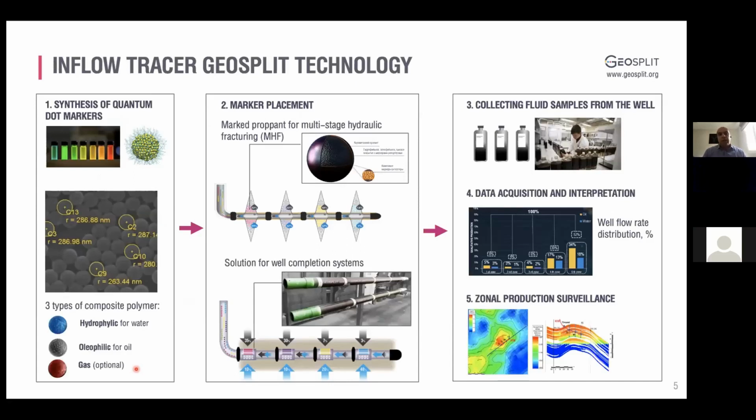I'll start by explaining the inflow tracer technology workflow. As I mentioned, what we use as a basis is quantum dots, which are nano-sized solids or crystals, typically between 2 and 10 nanometers in size. They are chemically, biologically, and physically stable, so when they are exposed to a harsh reservoir environment, they preserve their properties.